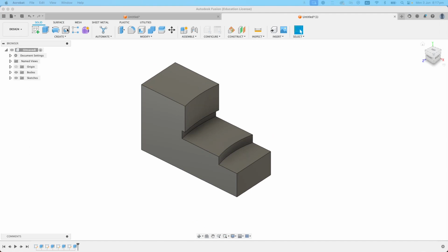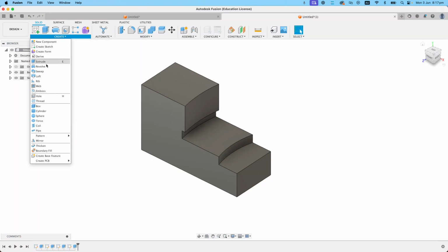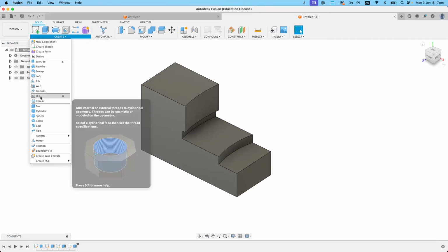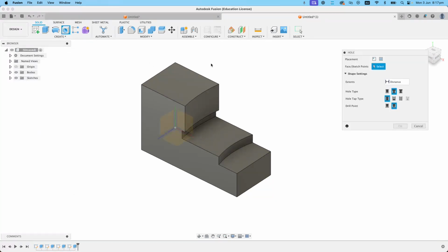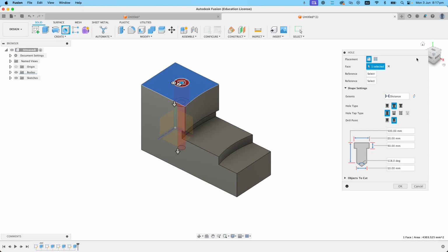All right, hole tool, check this one out here. If you haven't seen it before, it lives in the create menu. There it is, shortcut is H. I'm just gonna grab it, and I'm just going to place it on this face anywhere. I'm going to click somewhere there. Now, for many of you, you've probably got a simple hole.